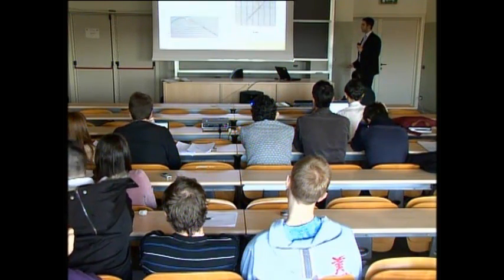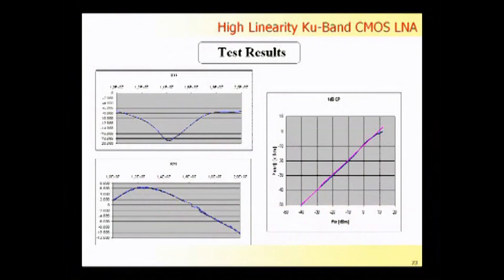After this result, we made an electromagnetic simulation of the ST inductor, and we extracted a model, and we saw that the ST model was wrong. So in the future, we have to extract the inductor model ourselves. The 1 dB compression point, so the linearity, is worse than the one simulated. This is because the gain goes down.